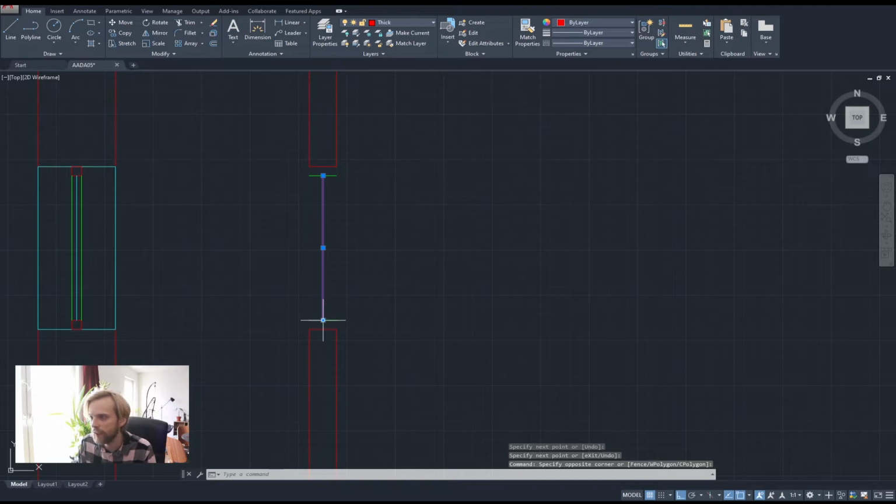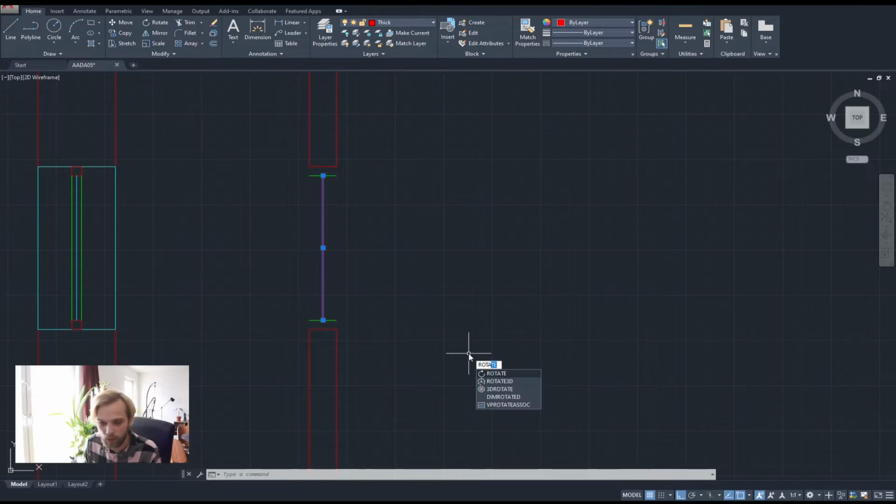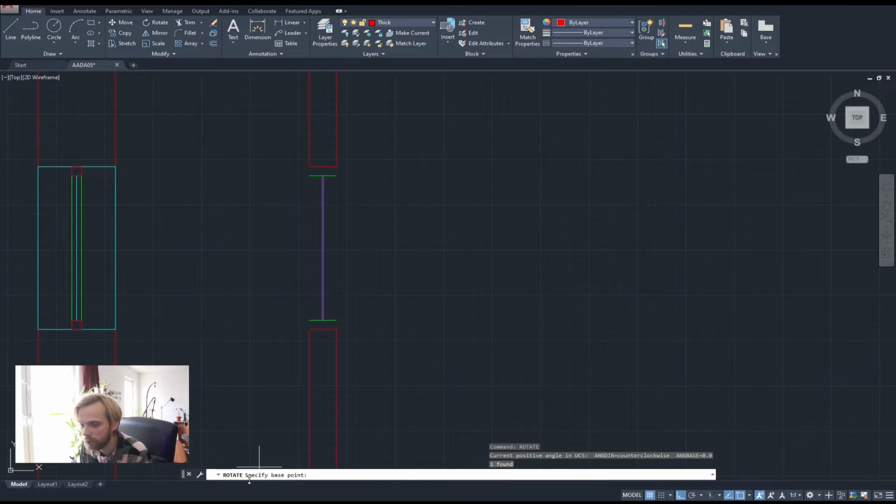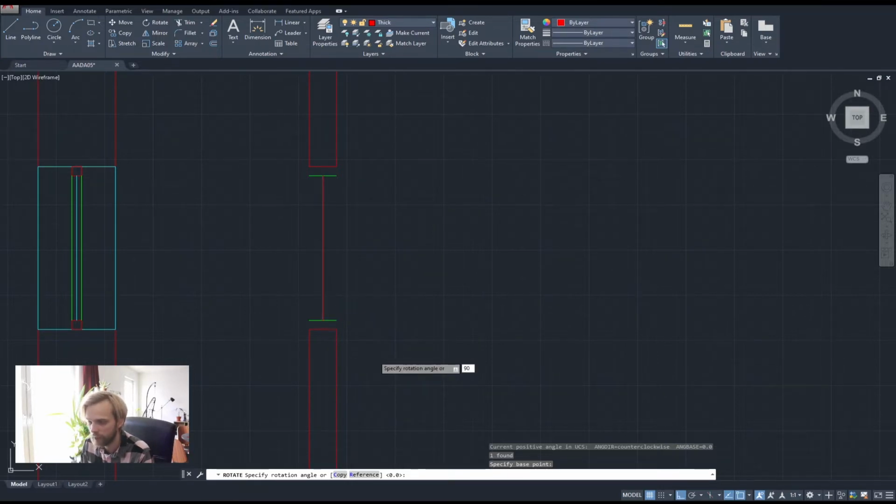I select it, and now I want to open up the door, right? So this doorway, or this door board, I want to rotate it, right? So I'm going to use a tool that's called rotate, enter. It's going to ask me for a point around which I'm going to be rotating. So let's say the door hinge is right here, that point. And basically then I can either move the mouse like so and click, or I can type in 90 degrees and hit enter.